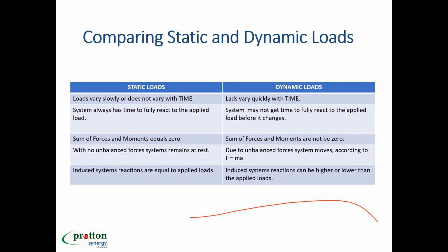If you're vibrating by your hand, it means that you're giving a force which is continuously changing its direction. Now the induced system reactions are equal to the applied load. Means if you apply a force of suppose 10 kg as a weight, then you will get the same reaction from the support. But in dynamic analysis, the reaction can be higher or even it could be lower. That is based on the response characteristics of the system.